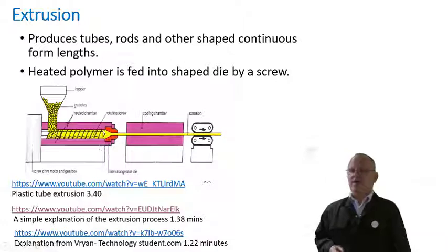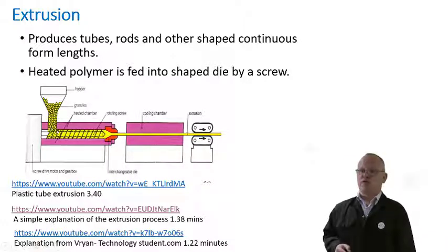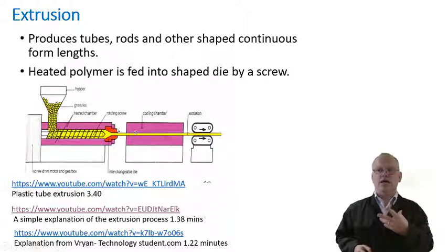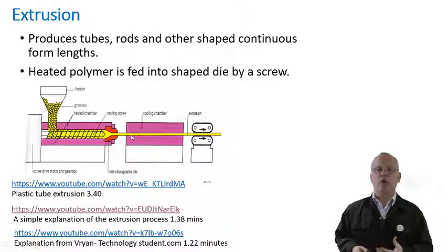So if we go back to our diagram, we've got the hopper, we've got the screw, we've got the die. When it comes out, if you imagine it to be a kind of a sticky, gooey material, it has to be cooled down so it goes through that transition state and it becomes more solid and holds its profile, because it has to be precise. So it goes through a cooling chamber. Sometimes this is a bath of water, and it's constantly refreshed to bring that temperature down, which causes that polymer to hold its shape. And it's drawn through, it's pulled through in sort of flattened areas.